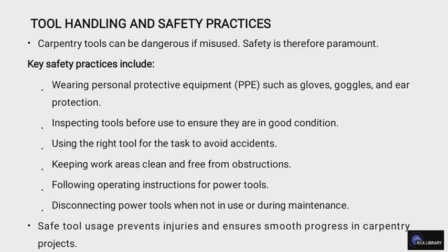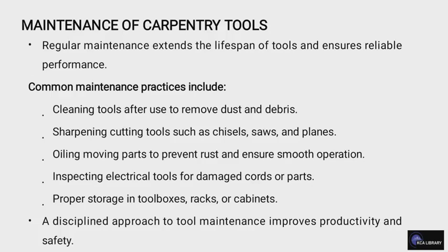Also, using the right tools for the task to avoid accidents is very important. You need to keep the work area clean and also free from obstruction. You need to follow operating instructions for power tools. And lastly, you need to disconnect power tools when not in use or during maintenance. Safe tool usage prevents injuries and also ensures smooth progress in carpentry projects.